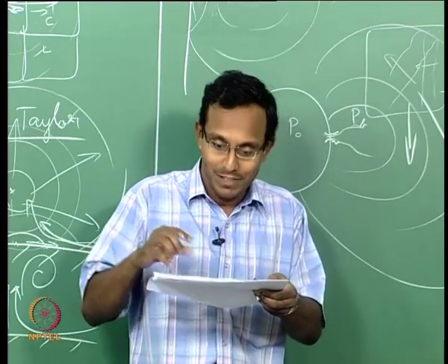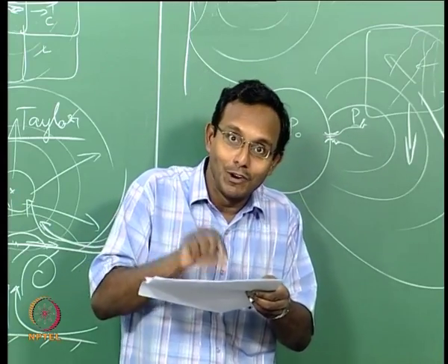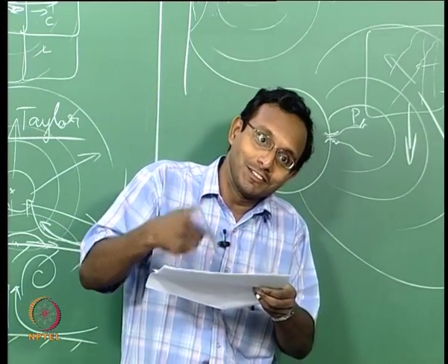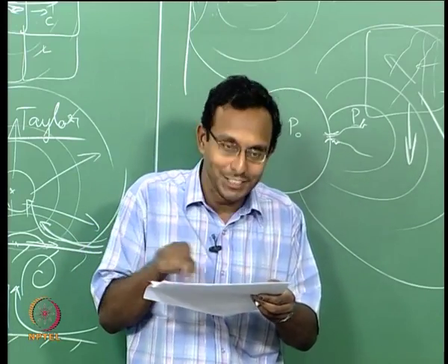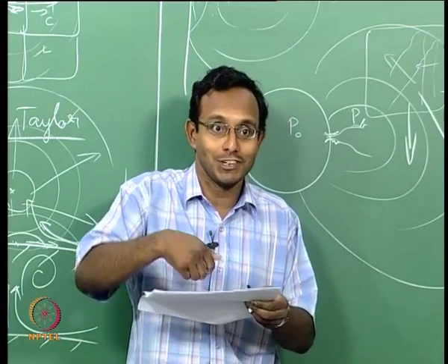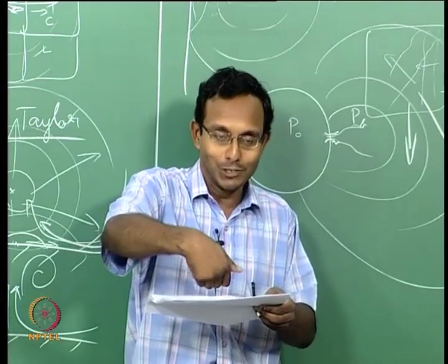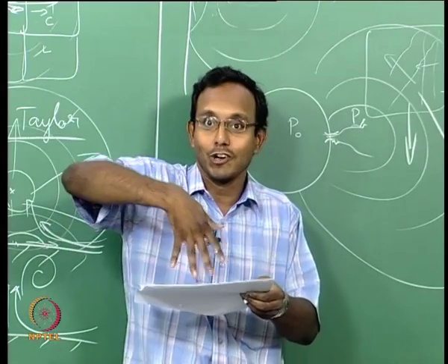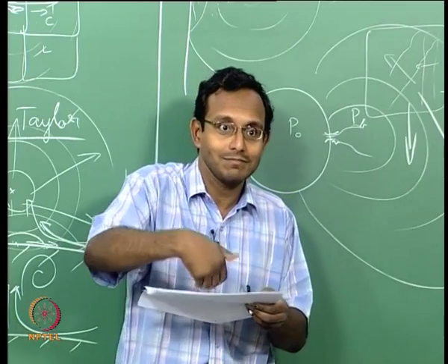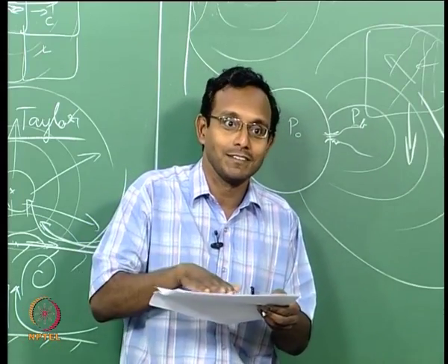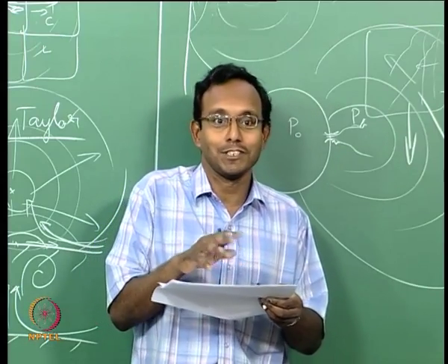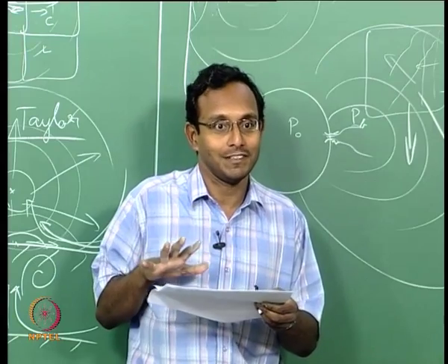During this whole time there was multiple bouncing up and down of this compression wave, which is compressing on top of each other. So the pressure inside is getting very high, but on the sides it is escaping continuously. So pressure is dropping from the sides. When the flow is going out this way, it is like a shock tube problem. Expansion fan comes from outside towards inside. From the sides it is getting expanded, from up and down it is getting compressed. Overall it will increase pressure to some extent. That is what we will get.